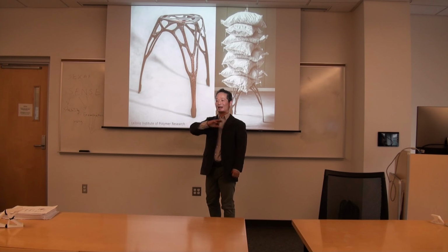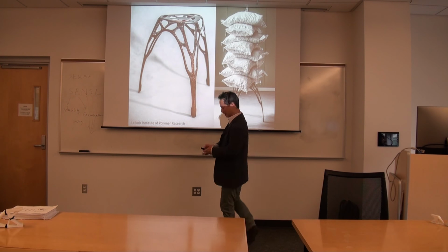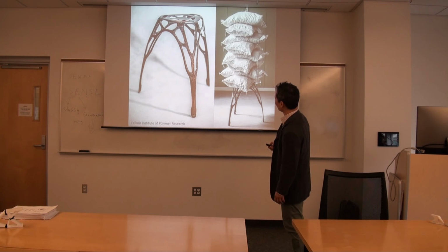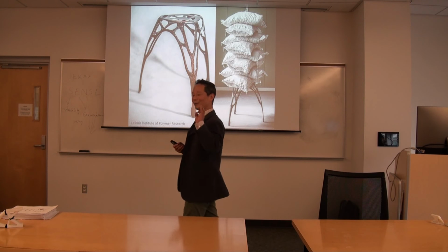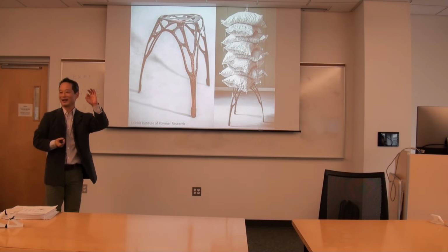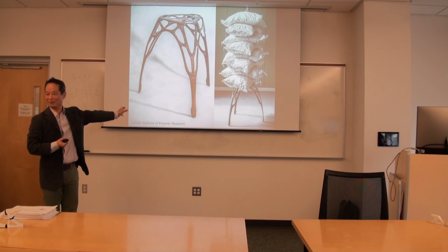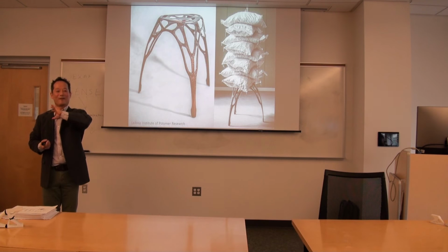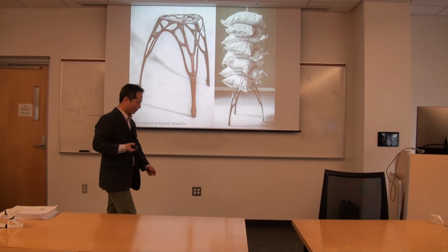Because you can lay fibers in an arbitrary direction, in this stool you could do this in one path, another path you are doing this, another path you are doing this, so that the choice of path is pretty much arbitrary because of the versatility of the process. And that, in combination with the resin molding, provides very superior structural performance.